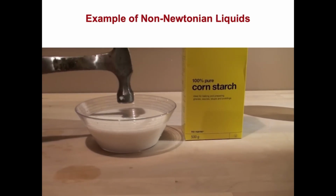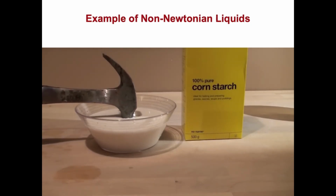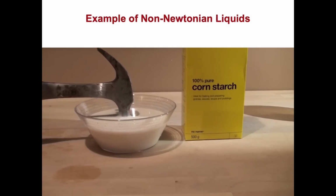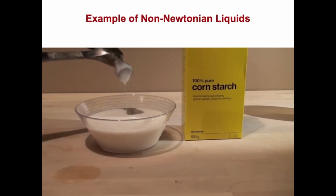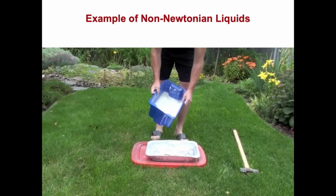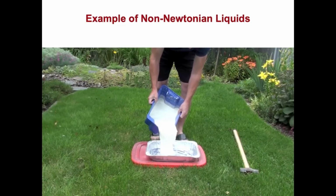If he hits the hammer slowly, it can enter. As soon as he hits it fast, essentially it's increasing the velocity gradient, so the viscosity changes. So the viscosity is not a constant. It's a function of velocity gradient itself. That's the whole point of a non-Newtonian liquid, that it does not stay constant. The viscosity can change and it is dependent on the velocity gradient.